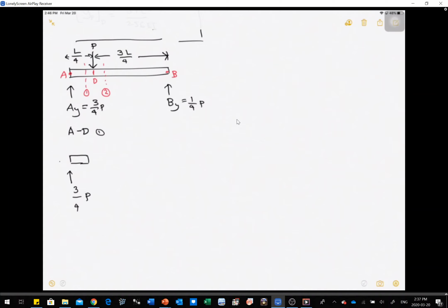And here, this is your shear. We cut our section, and that's going to be our moment. Let's call it M1 because eventually we're going to have M2 when we do section number 2. Actually, we can even call this one our V1, but right now we are interested in our moment. Now for section A to D, we get the moment at this point, and note that this is our X for this specific section. Again, this is just for AD, right here.